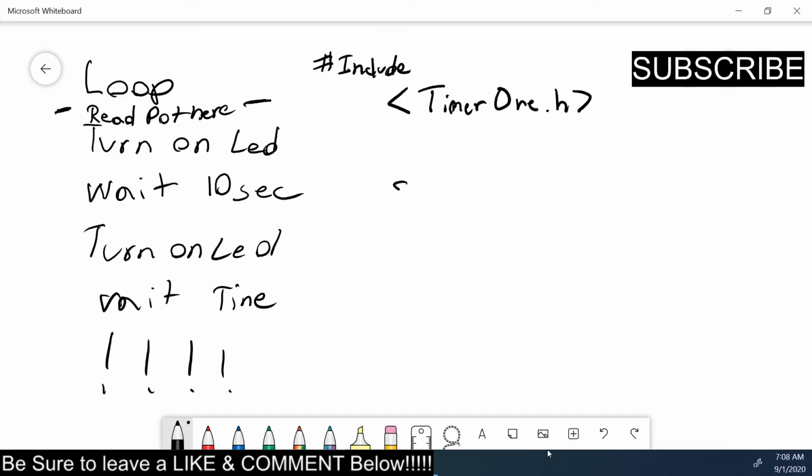So you're going to set it up and tell it however many microseconds you want it to wait to do that interrupt and check whatever function you want to check. So say I want it to check every second, so 1 second in microseconds is 1,000,000 microseconds.